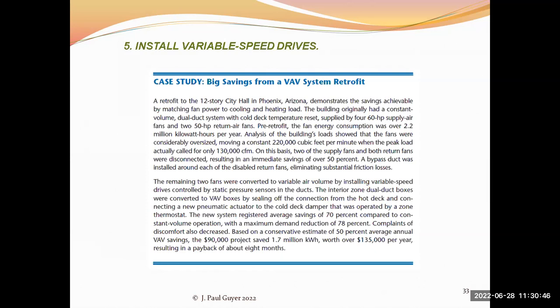And in this particular building, there were 460 horsepower supply air fans and two 50 horsepower return air fans. In this example, the fan energy consumption was over 2.2 million kilowatt hours per year. And analysis of the building's load showed that the fans were considerably oversized, moving a constant 220,000 cubic feet per minute of air, when the peak load actually only called for